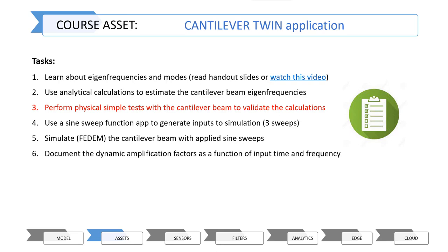Perhaps you have also been wondering if my simulation results really match the physical behavior of a cantilever beam or any other structure. And now I'm going to show you how I have been using a sine sweep function, a physical test rig and a high-speed camera to validate the eigenfrequencies and mode shapes of a structure.